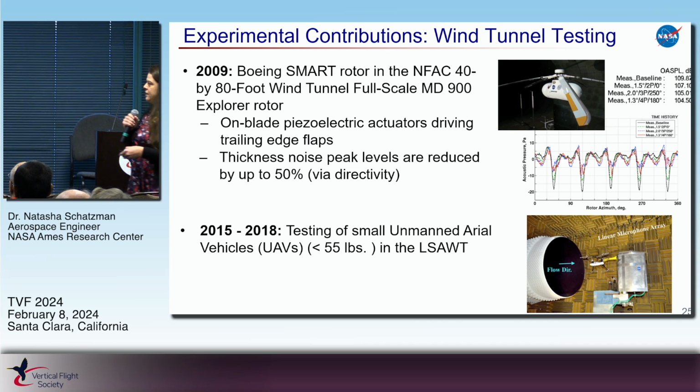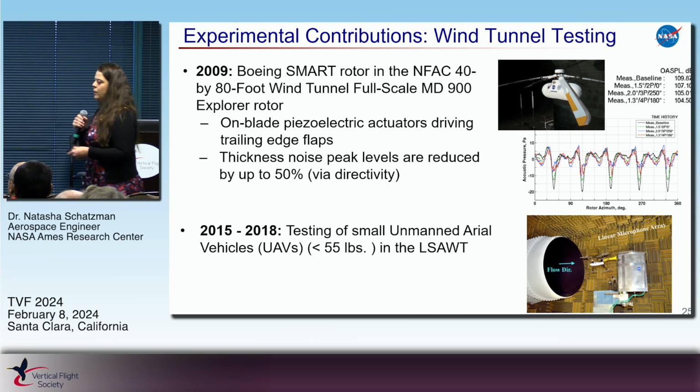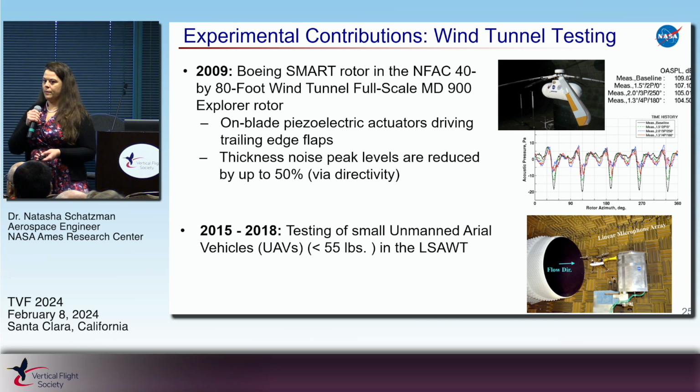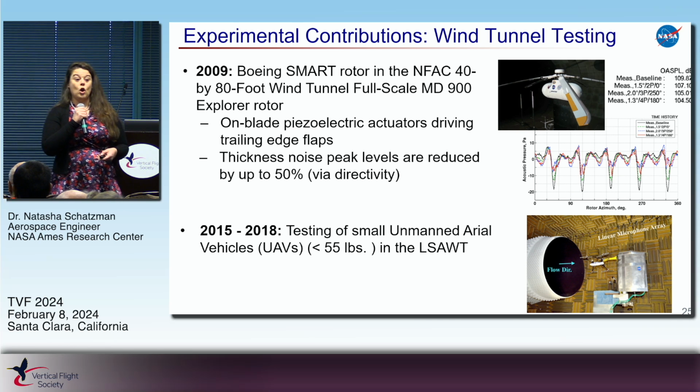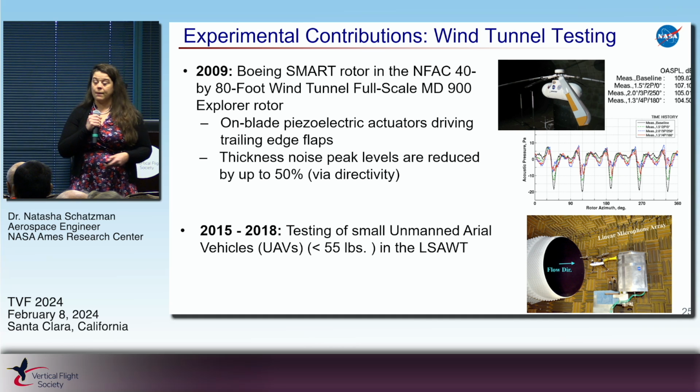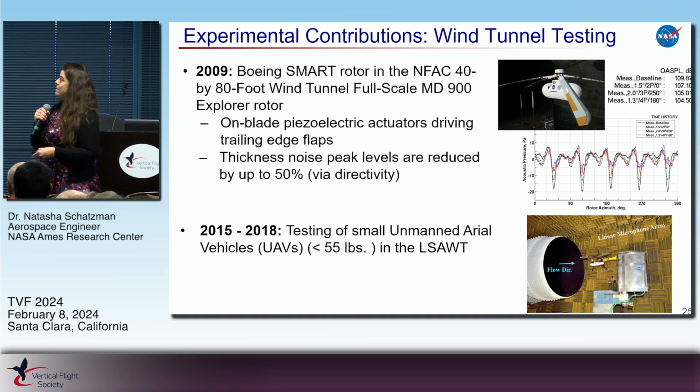Moving on to 2009, I know Rom is going to enjoy this one. We have the Boeing Smart Rotor in the 40 by 80 foot wind tunnel, which implemented piezoelectric flaps in the blade on an MD-900 Explorer rotor.